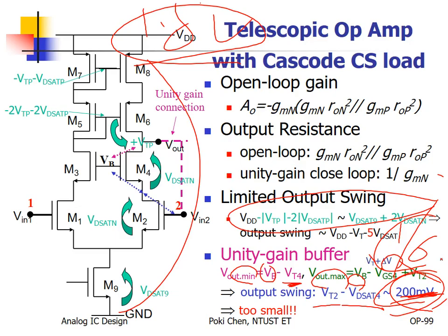Why I told you for voltage buffer, usually the gain is not so high. 100, good enough. Why? Because the higher gain means the smaller operation range for the best performance. Okay? Got it? Nothing is free. You need to pay for it. If you design a higher gain for the voltage buffer, its best operation range will shrink significantly. So we usually don't do this kind of silly thing. Usually, we don't design a very high gain for such kind of voltage buffer.